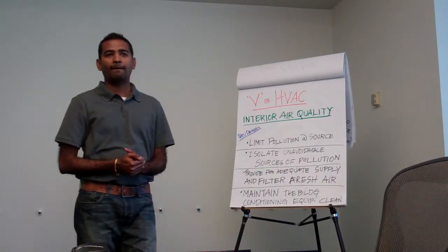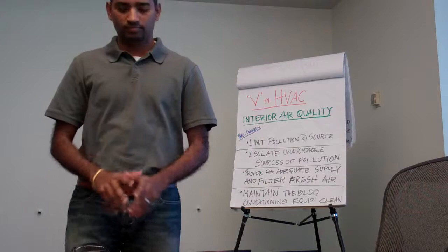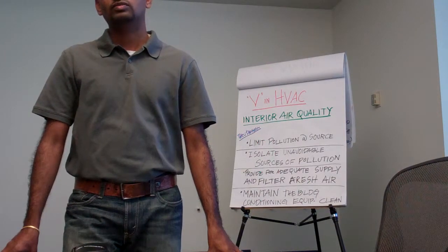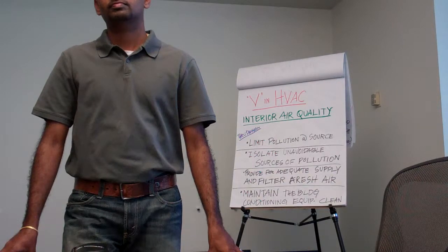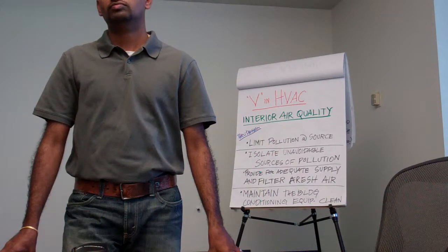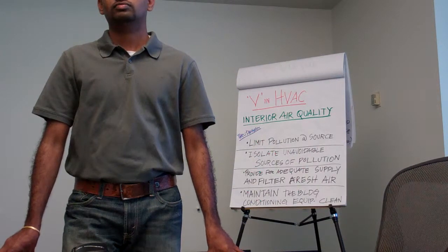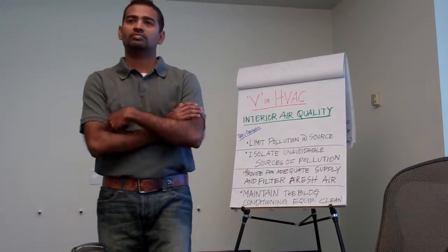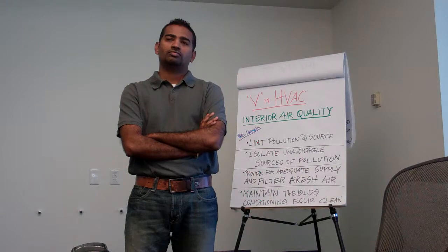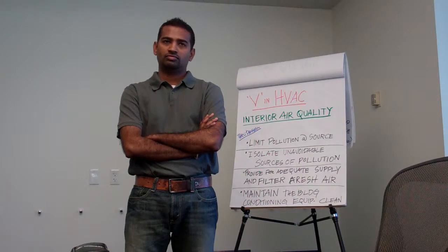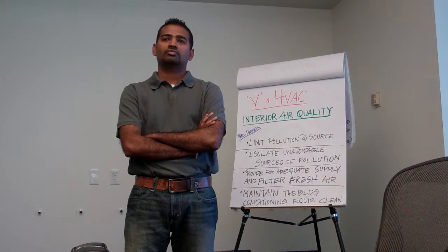But then if you reduce the VOCs of your finishes or your components, you can't use those new numbers. You can't use the actual VOC content of your components. The ventilation code, ASHRAE, is the standard. The latest codes are adopting those ASHRAE standards that start with the area, a minimum amount of CFM per square foot per area, and then have an additional calc for the CFM per occupant. And if you're using CO2 sensors, my understanding is that I'm reducing the amount of outdoor air down to the minimum by area because VOCs don't come out as CO2. So I'm not sensing VOCs. There are other things I could use to sense VOCs, more controls, to reduce it down to nothing.